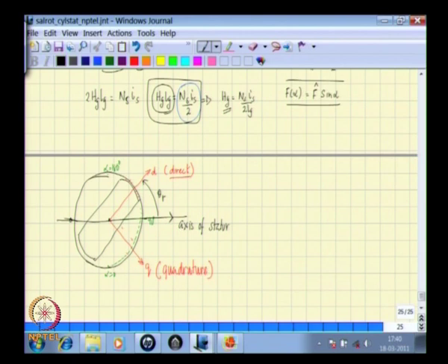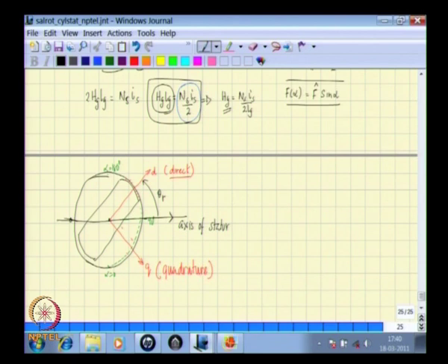Now we say therefore that the rotor is at an angle 0 if this rotor bar were horizontal, and we say that the rotor angle is equal to 90 degrees if the rotor bar were arranged in this manner. So that is then the rotor angle. If this is the rotor angle, then by geometry what one can see is that this angle is also the rotor angle, because these two axes are oriented 90 degrees to each other. So with this then what we want to do is to try and resolve this MMF, stator MMF, along these two axes.